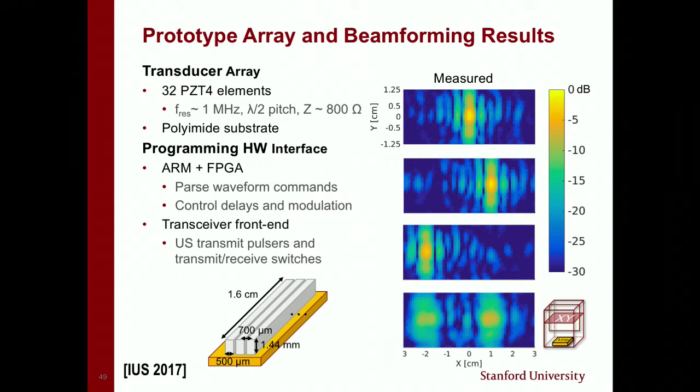And we can do simultaneous multiple beams. So this is essential because I want to talk to multiple implants simultaneously. And so I need to generate multi-beam functions. And as you can expect, when you have a multi-beam, you sacrifice the number of elements in each of these beams. And so the beam widths are slightly larger.